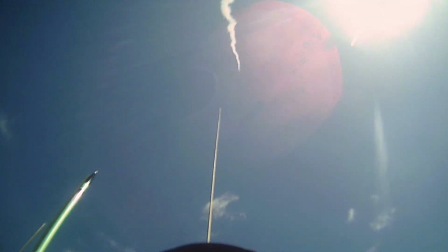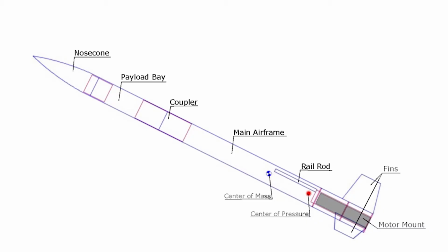However, people would simply add clay to the nose cone because it would be better to be overly stable than not stable at all. To ensure stability, the center of pressure must be closer to the motor retainer than the center of mass, and adding weight to the front of the rocket at the nose cone would shift that center of mass, so that was the case.